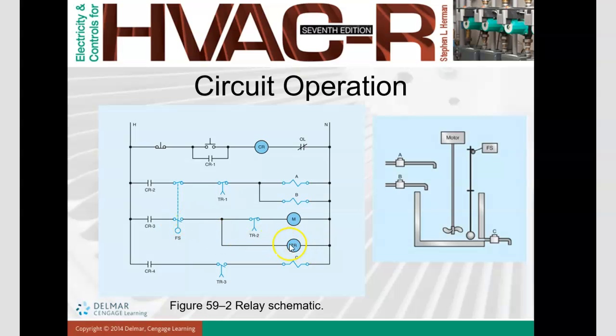So this time relay will not have any current, meaning that all the contacts go back to original. This open, this is also closed, this is also closed, and then solenoid valve 1 and 2 will function and fill up the tank again until this button is pushed.